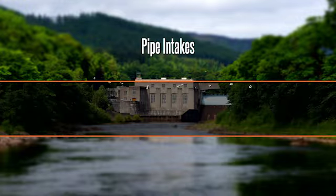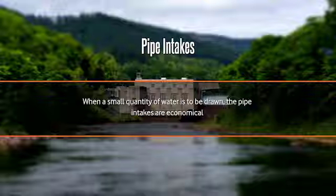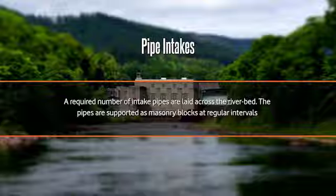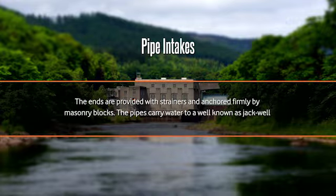Pipe intakes. When a small quantity of water is to be drawn, pipe intakes are economical. A required number of intake pipes are laid across the river bed. The pipes are supported on masonry blocks at regular intervals. The ends are provided with strainers and anchored firmly by masonry blocks. The pipes carry water to a well known as a jack well.